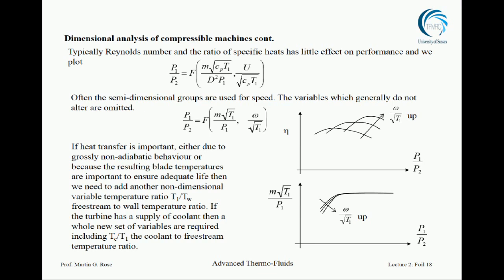And if the compressor is rotating slowly and generating low pressure rise with low volume flow rate going through it, that's all right. Where the problem comes in is when it's rotating fast with low flow, then it's in trouble. It will just go bang, bang, bang, bang, bang until you switch it off.